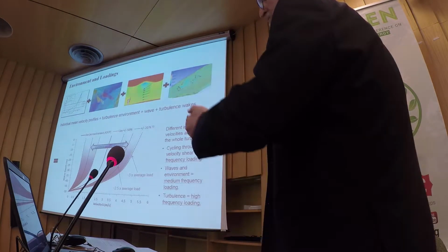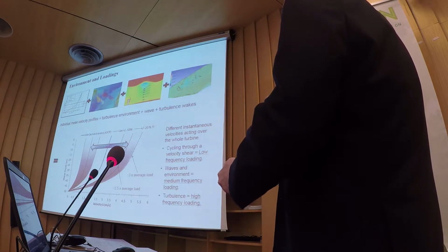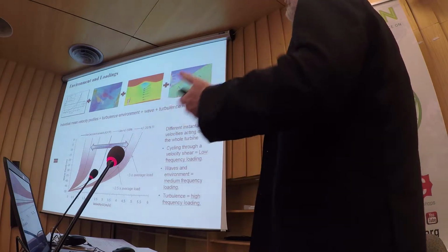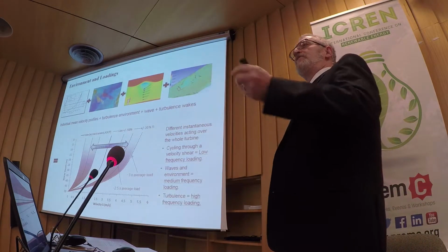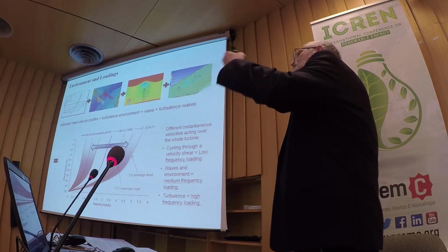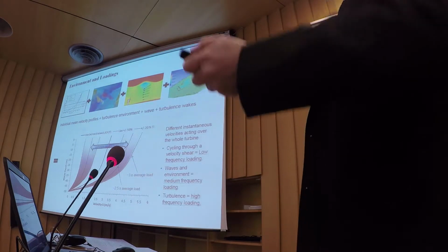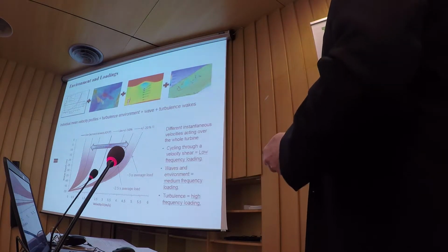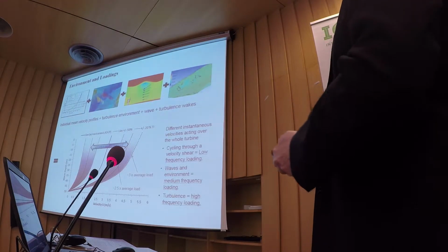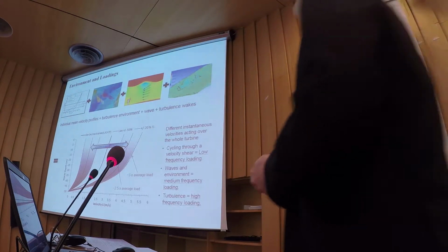So to combine that all, you've got a velocity shear, possibly, and in that case, something like 2.5 times the load when the blade is at the top compared to a blade that's at the bottom. So it's a fairly extreme case. Then you've got to take into account the bathymetry and whatever islands or headlands are upstream, creating those eddies that are going to be shed off it.